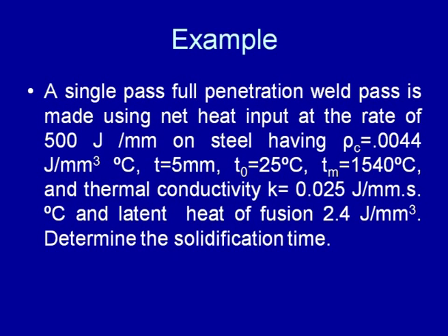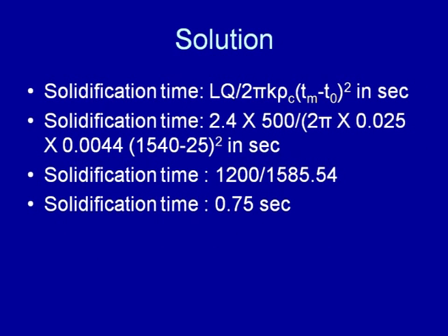Then the solidification time can be obtained using the simple cooling equation, which shows the solidification time is equal to L, the latent heat of fusion for the material being welded, and Q, the net heat input being given, divided by 2 pi K, thermal conductivity, rho C multiplied by Tm, the melting point, minus T naught, the initial plate temperature, and this gives us the time in seconds.